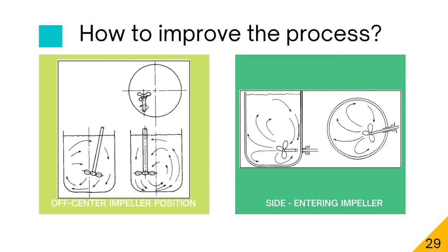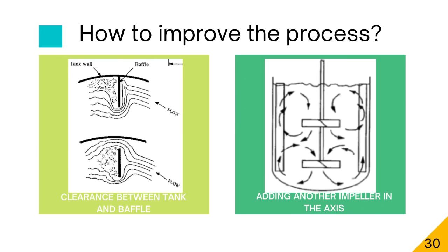Reducing vortex formation may also be achieved by placing an impeller in an off-center position. This creates an unbalanced flow pattern, reducing or eliminating the swirl and thereby increasing or maximizing the power consumption. The exact position is critical, since too far or too little off center in one direction or other will cause erratic swirling, erratic vortexing, and dangerously high shaft stresses.